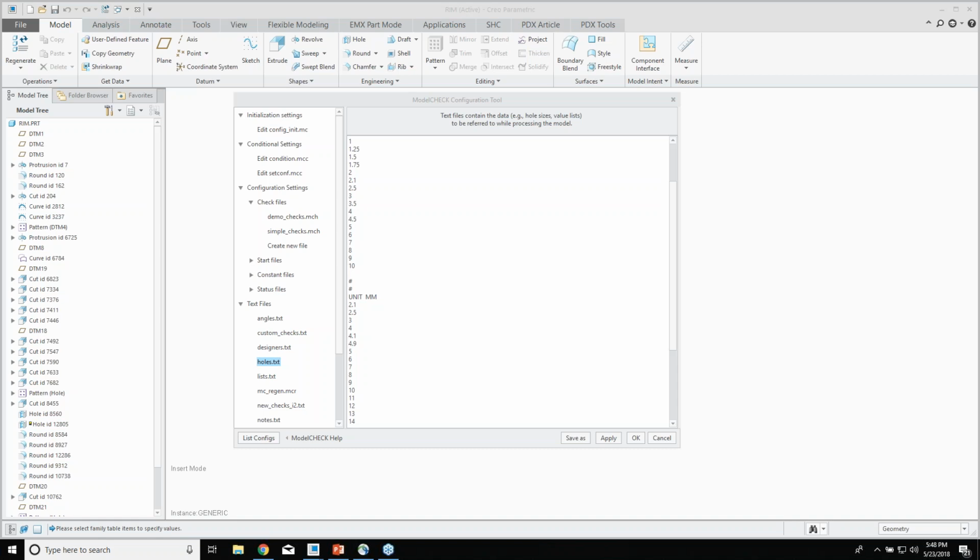And then the second part of the question, will settings need to be converted when we upgrade? That question, yes. So all these files that I'm talking about now, your initialization settings, your checks and things like that, you will have to copy that over to the new installation. I'll also keep a backup of that, but that depends on how you manage it. You can have all these things out of the installation directory, and it will be driven from the config.pro file.